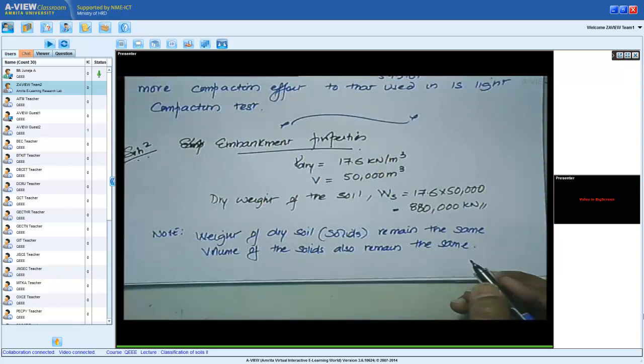Under most engineering loads, the soil particles are assumed to be uncrushable. You can't crush them under routine loads, unless you're dealing with some kind of calcareous deposits. For example, these deposits are mainly found in marine environments, made of seashells, and those are the ones which will crush.